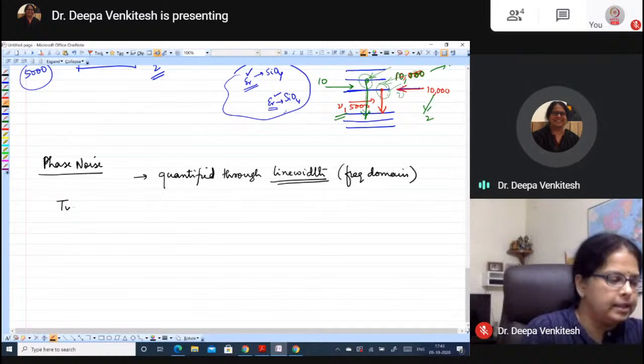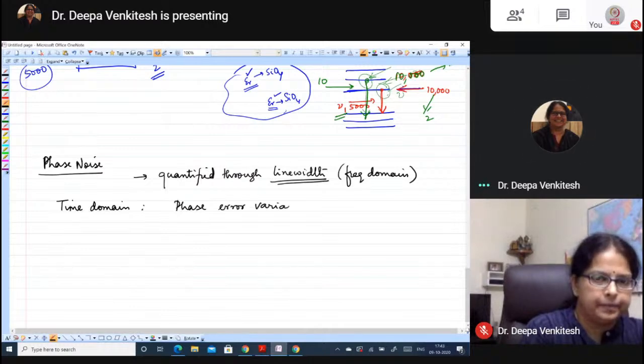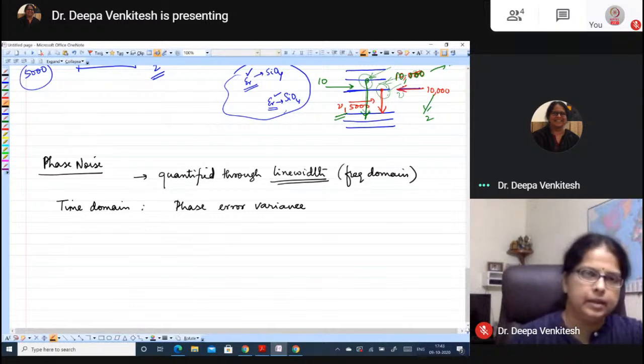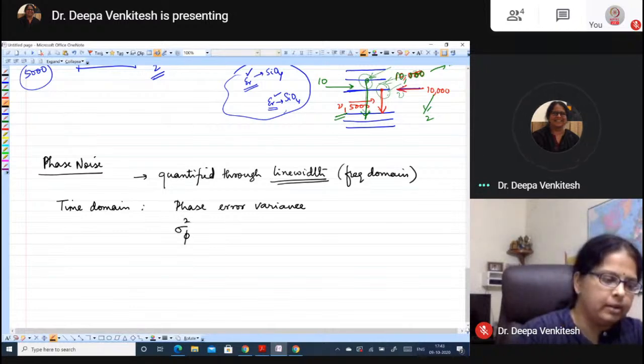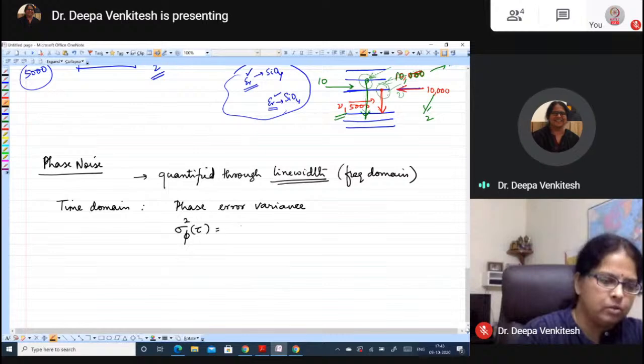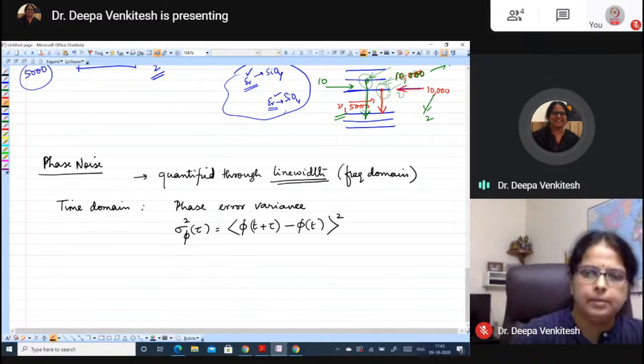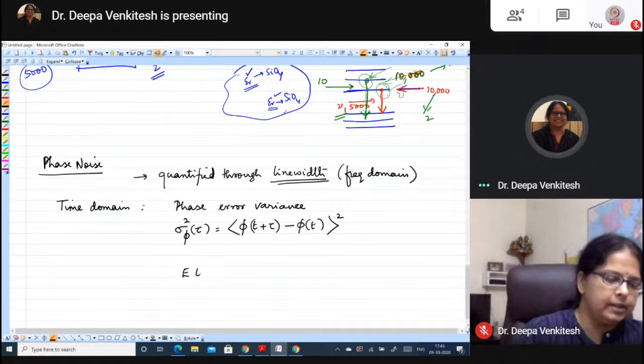We studied in the class that we can also quantify it in the time domain through what is called phase error variance, sigma squared of tau, which is the variance of phi at t plus tau minus phi of t.